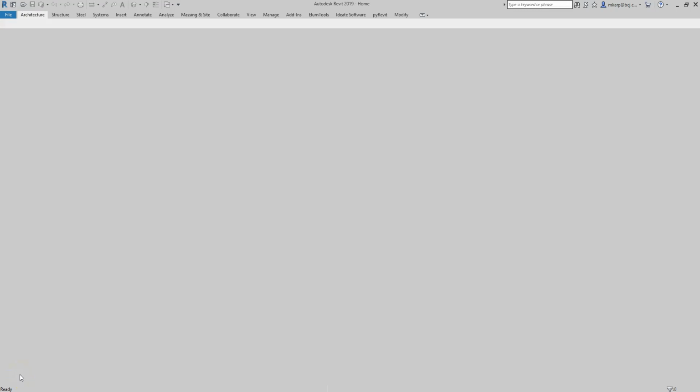Alright, in this first video for this semester, we're going to go over how to make the site plan for your project and how to start a REVIT file and go over some basic things such as importing AutoCAD files, setting the location of your project, creating a Topo Surface and adding some regions to that Topo Surface to work as roads. And then we're also going to get into some slight massing and working with levels.